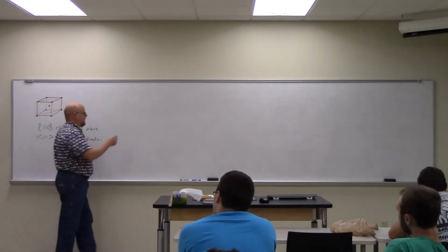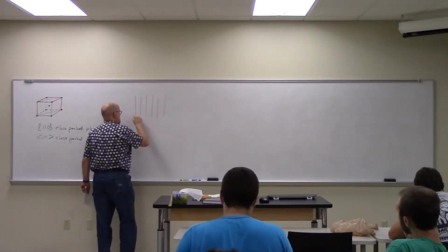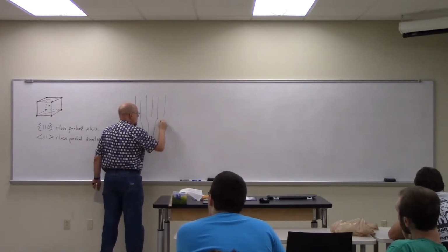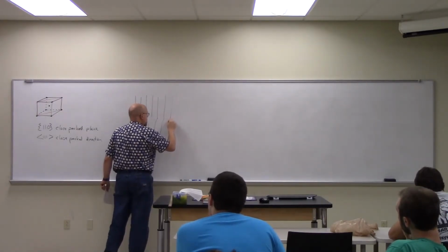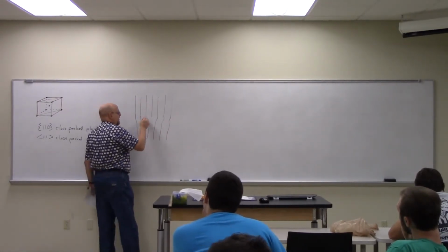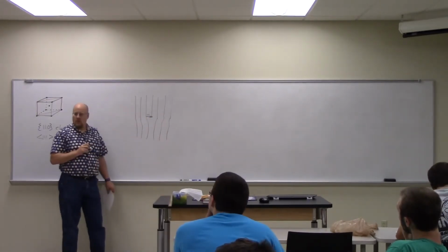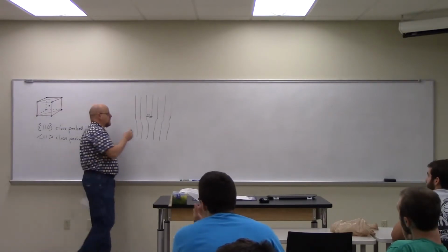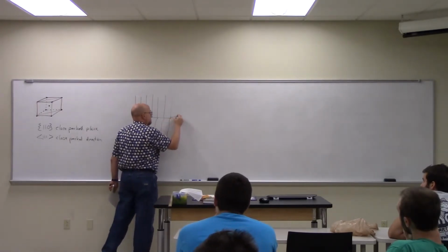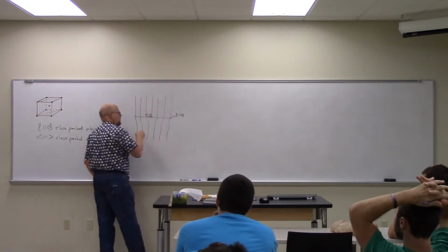So in my structure, this was my thing, and then kind of did this, and something like that. That was kind of the general structure. So what that says is that this direction is the 111 direction in BCC, and this plane on which that thing is sliding is the 110 plane, or family plane. It's a 110 plane and a 111 direction.